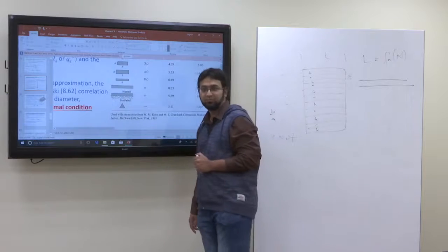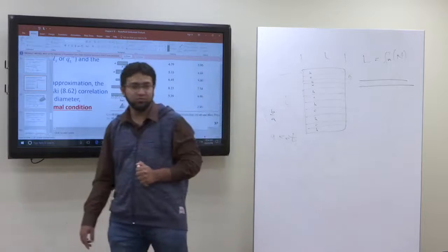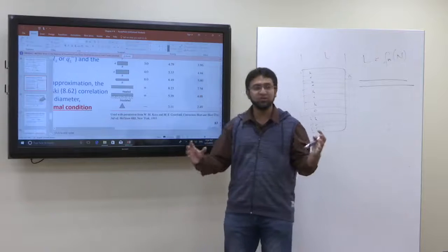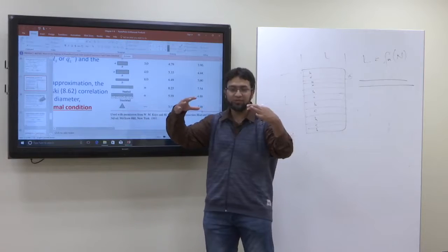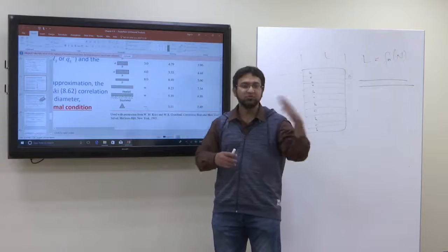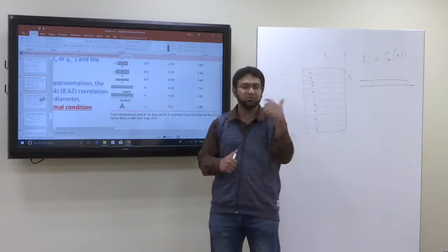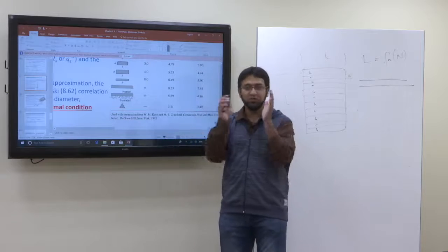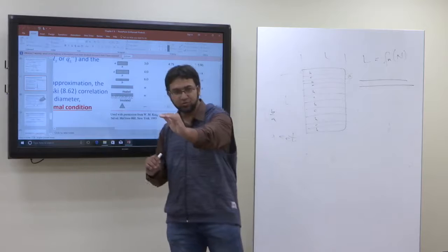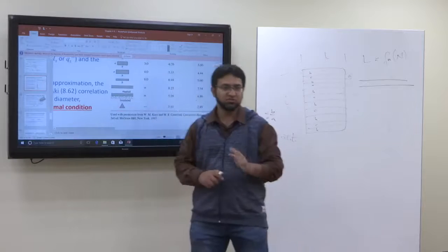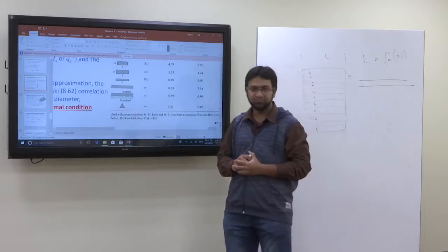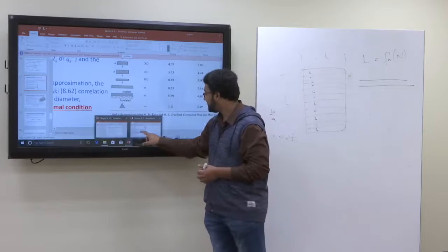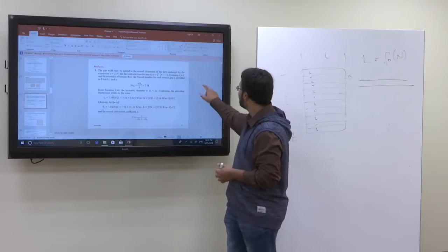How do we know it's uniform surface temperature? It could be assumed as uniform surface temperature, because for the cases of uniform heat flux, you have a certain source of heat flux all the time, whether it is solar or an electrical heater. But we don't have any certain source of heat flux, and we know a specific temperature which is flowing through the tubes, so we assume that it's a constant surface temperature. Is that clear? So it is 7.54. Let's come back here.